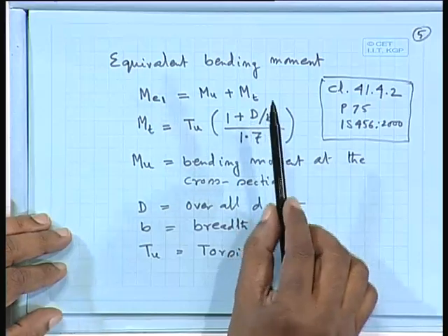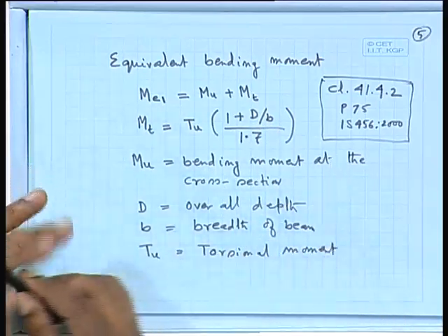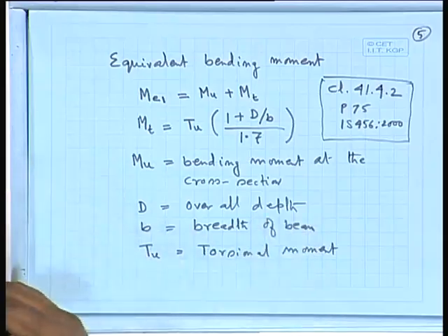But finally we come to this 1.6, 1.7 for design purpose, so that it is applicable for a wide range of rectangular sections or beams. That is the objective here, how we come to all the clauses wherever you have different parameters. Sometimes we find the modulus of elasticity E, that is 5700 root over fck. If one is interested in design, from the analysis or from the experiment, one can find the value, maybe it is coming 5200 or 5300, but finally we come to that particular value so that it is applicable to a wide range.